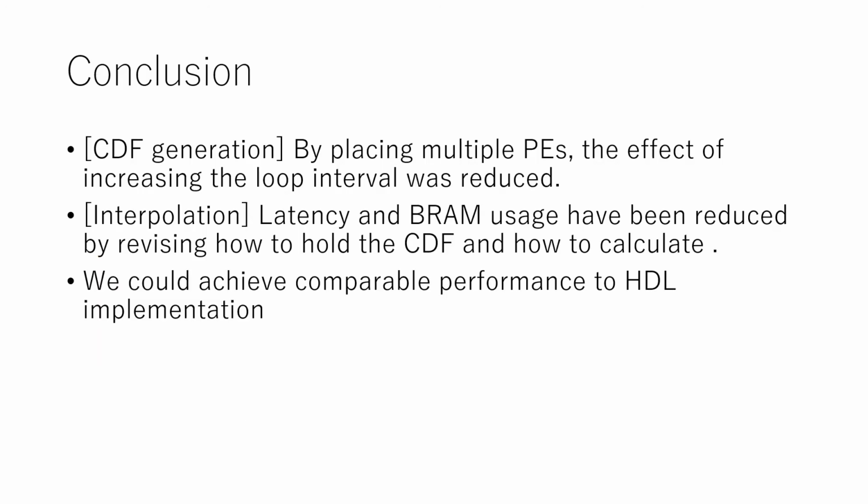Conclusion. We talked about the design of CLAHE. In CDF generation, by arranging multiple PEs, the effect of increasing the loop interval was reduced. In interpolation, latency and VRAM usage have been reduced by revising how to follow the CDF and how to calculate. As a result of this technique, we were able to achieve almost the same performance as the HDL implementation by high-level synthesis. Thank you.